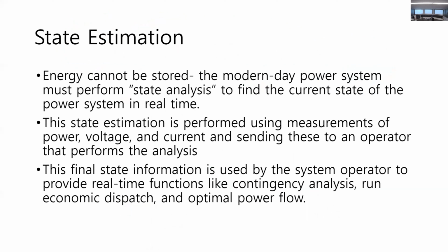Although we cannot measure all electrical quantities throughout the entire power system, given a state, or the minimum amount of independent variables, we can find all other variables as dependent functions. You can kind of relate this to the states and state variables we learn in linear algebra. This state can be estimated with measurement values of power and voltage coming from local control centers and SCADAs. SCADA stands for supervisory control and data acquisition. Just think of these as very big and complex tools that monitor electricity at various points throughout the power system.